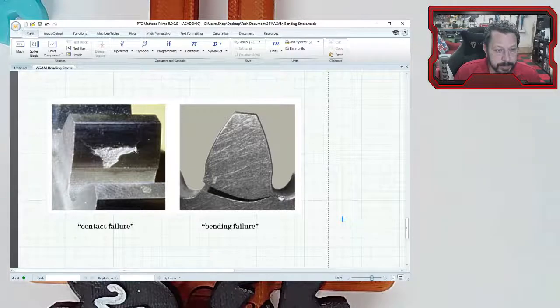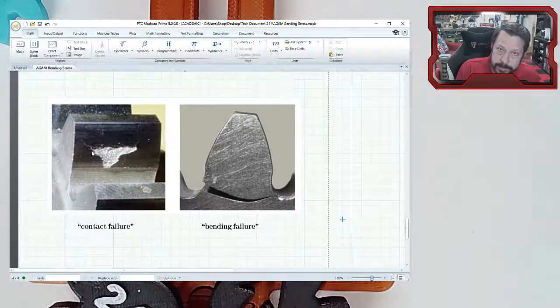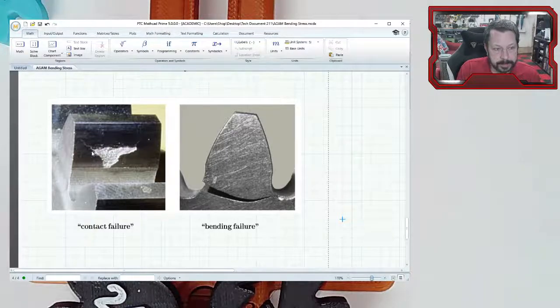Now this particular picture has a line, but then a big chunk broken out. These teeth are undergoing some compression. The teeth are pushing on each other. Below the surface, there's this harder, work-hardening type thing underneath the surface where there are these compressive stresses.